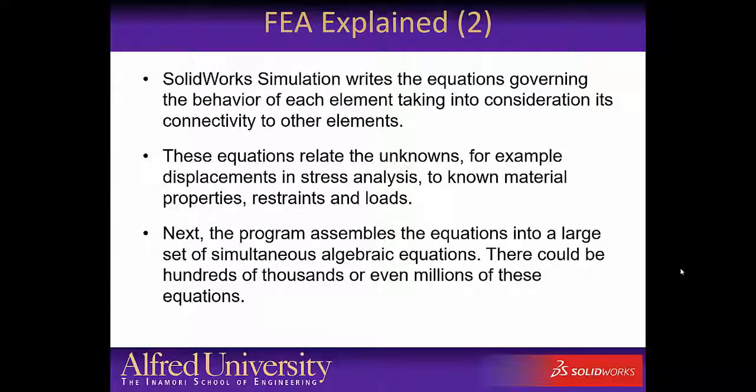Next, the program assembles the equations into a large set of simultaneous algebraic equations. There could be hundreds of thousands or even millions of these equations, depending on the fineness of the mesh and the size of your model. When local equilibrium is converged by solving these equations of state for every single node, then the large geometry of the overall part has been solved. This bypasses the need to create complex analytical solutions for general problems.